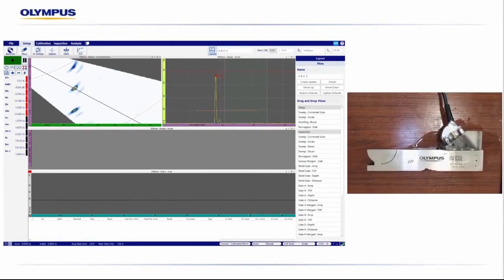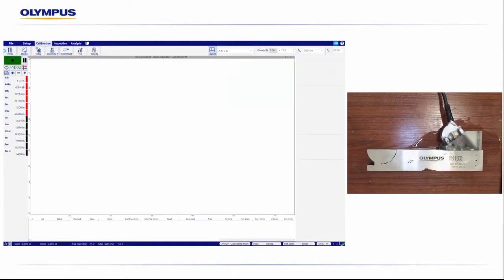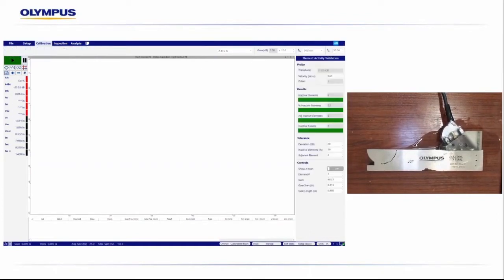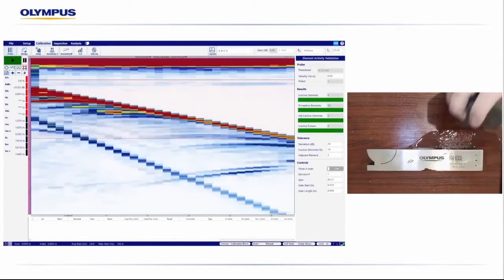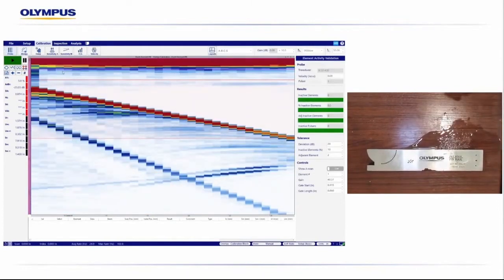So moving to the calibration tab on the top side of the screen, we'll click our probe check. So we've got our probe check, wedge check, wedge delay, sensitivity, AM, TCG, and your velocity. Within our calibration and our probe check, we can verify we don't have any active pulsars, inactive elements, anything like that. Same within our wedge check. That'll check our wedge to the default parameters from BeamTool, and that'll verify our wedge height, angle, and that everything is correct within the set specifications that we provide.